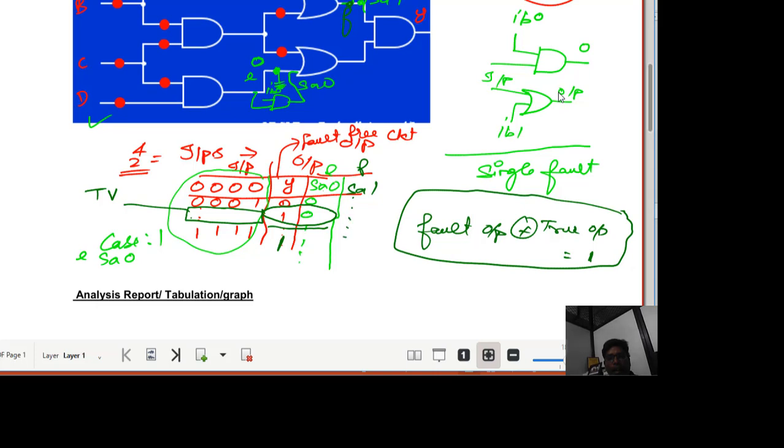Here for the faulty case let it be 0. Then in this case, there exists a difference between a faulty output and a fault free circuit output. The corresponding test vector is four ones. So this is the test vector. Then I claim that this particular test vector has captured this particular fault, that is stuck at 1 at node F. That's the simple idea.